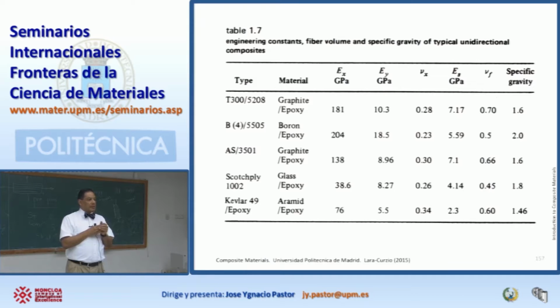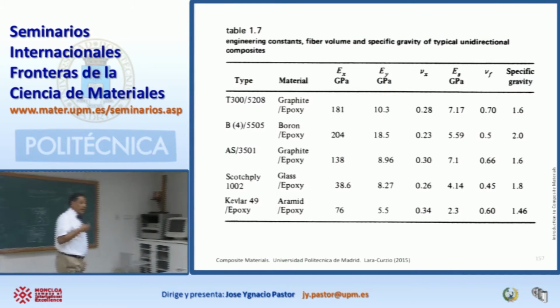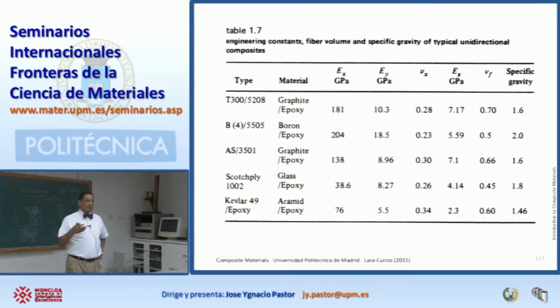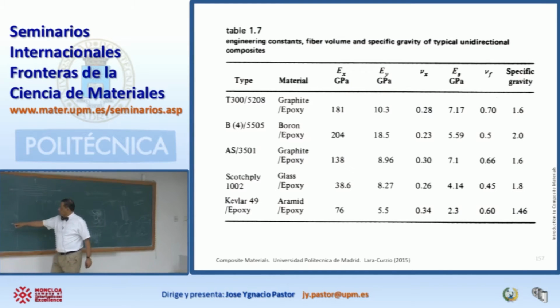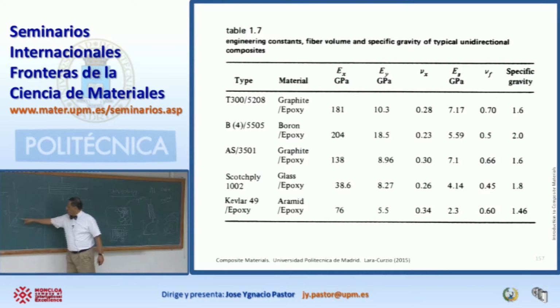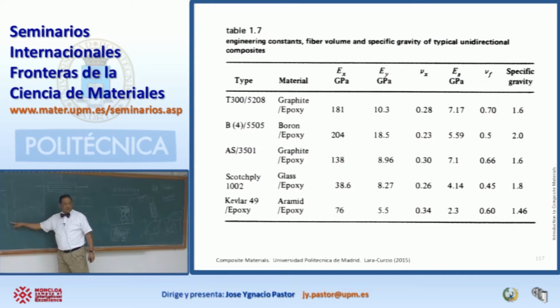In the case of ceramic matrix composites, the interface is relatively weak, but if you apply small deformations, everything's going to stay together. And remember that as engineers, we are never going to design anything beyond either yield for metals or polymers or beyond the matrix cracking stress for composites. So all these relationships will hold for most design applications. If you remember the ceramic matrix composite, the curves look like this, but you're always going to be working here up to the elastic limit.